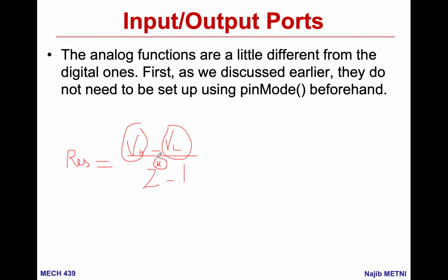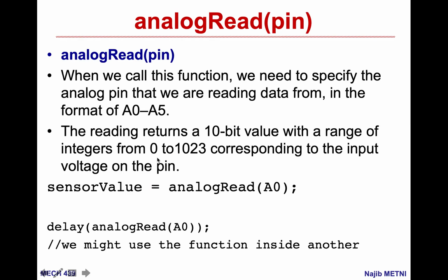The most important function here is called analogRead. I will be reading the value from the analog input. When we call this function, we put the pin in its parentheses, A0 to A5, depending on how I am connecting my signal to the microcontroller.